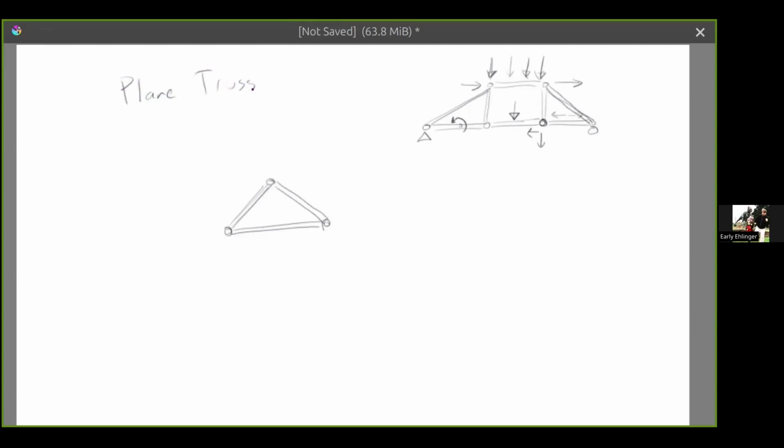So that was a plane truss. One thing I need to bring up very quickly about plane trusses is that the only types of supports allowed are pins and rollers. In a plane truss, you cannot have fixed supports. That again is because the idealization of the structure is that none of the nodes will transfer or resist twisting. The book refers to this as having hinged joints.